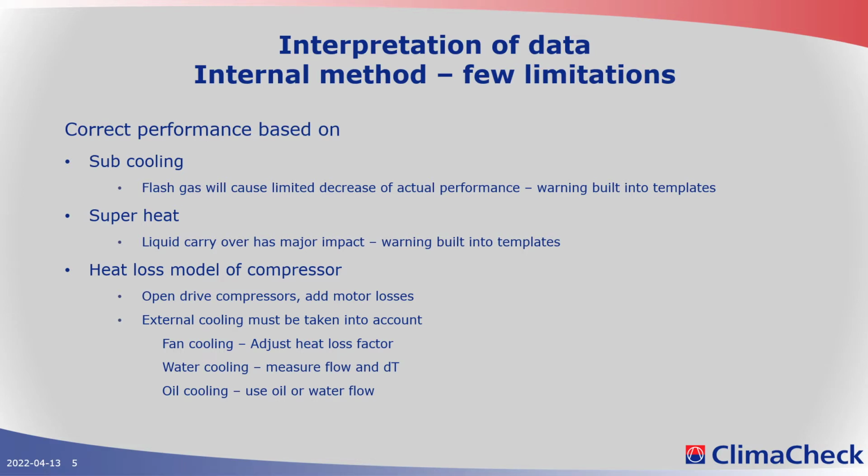Depending on what type of system I have, there is an expected superheat. And if I'm running with much higher superheat, there is an issue. And of course, the performance of the evaporator will be lousy if I have too high superheat. If I have too low superheat, I might even get liquid carryover to my compressor, and then nothing will turn out correct, and I might damage my compressor.